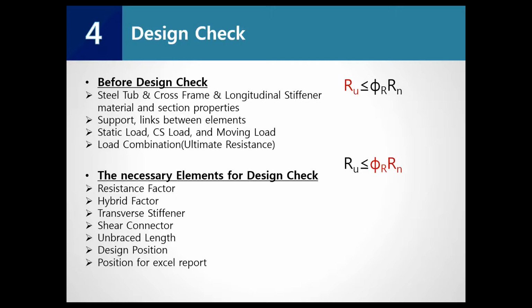Those material and section properties are defined in one steel top section bridge. And then, because you use the steel composite widget, supports are automatically defined, and you also made a pier cap and pier columns. So there is a link automatically generated between the substructure and the superstructure.